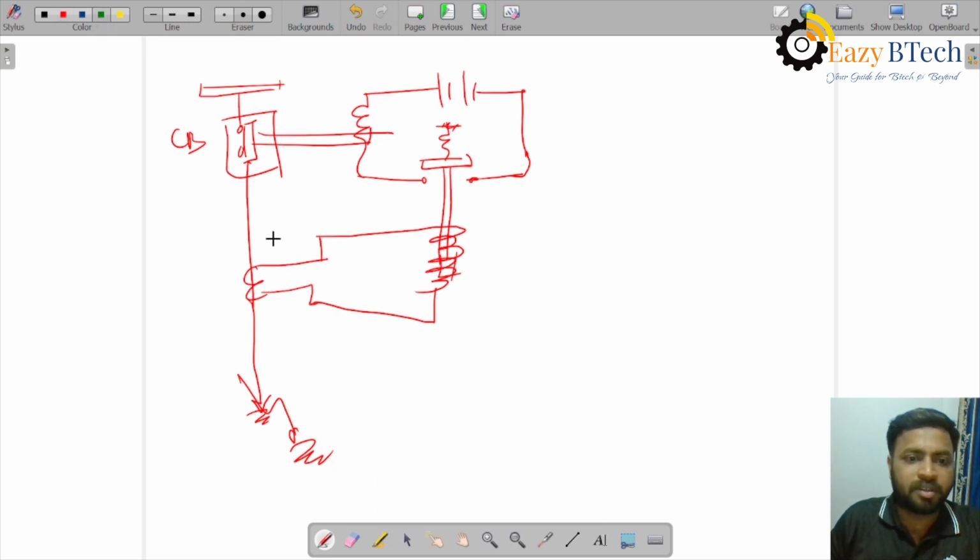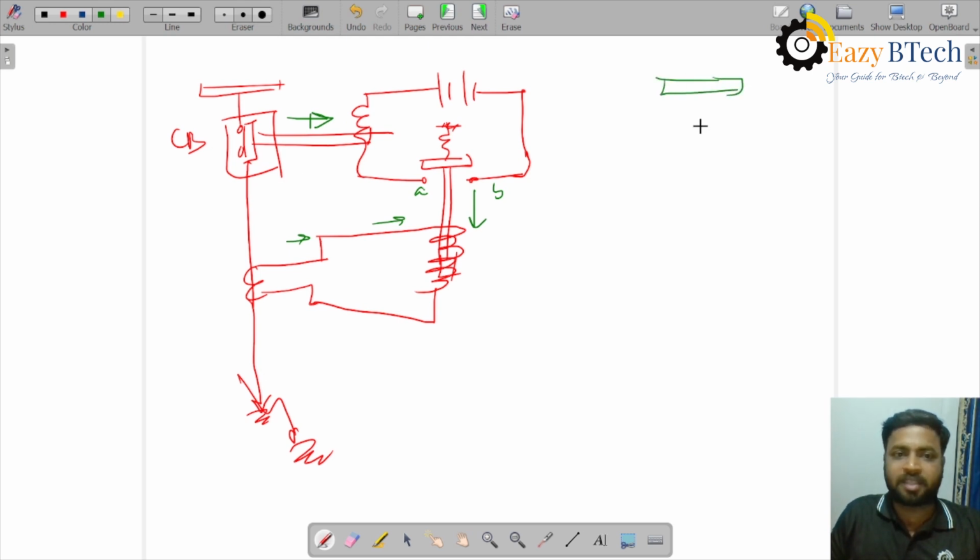So there is a fault, and due to the increase in current in the relay coil, the plunger is pulled down. In the sense, the operating torque created by the relay coil exceeded the torque or force generated by this control spring, and this plunger is pulled down and the trip circuit is closed. Once the trip circuit is closed, the circuit breaker moving contact is pulled apart and the circuit breaker is now in open condition. Normally the circuit breaker is under closed condition.